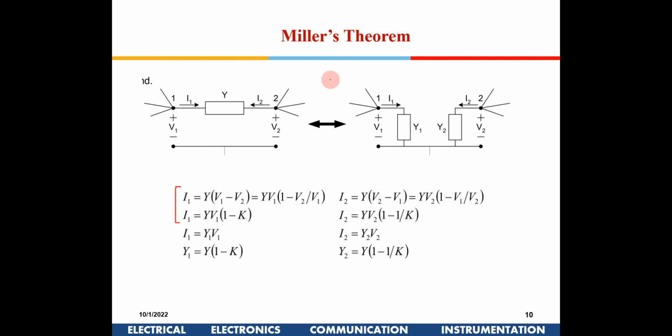Now I can represent this circuit like this also. What is this representation? Instead of having one impedance across this amplifier from here to here, I can put it into the input side here, because this will make the analysis easier. Like for a CS amplifier, between the gate and the drain, that capacitance is now represented here like this. If I am pushing it down here like this, it comes here like this, right? So now this is the equivalent circuit.